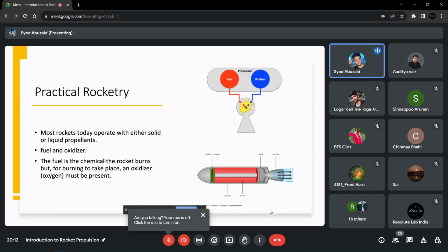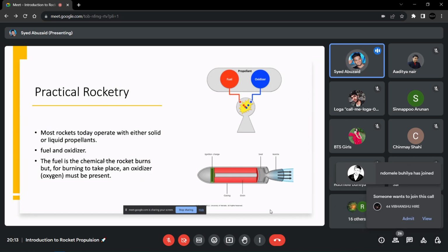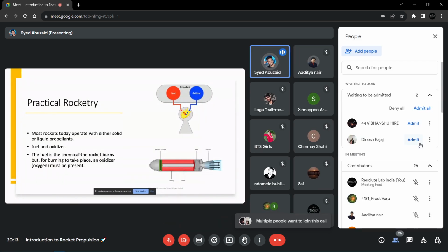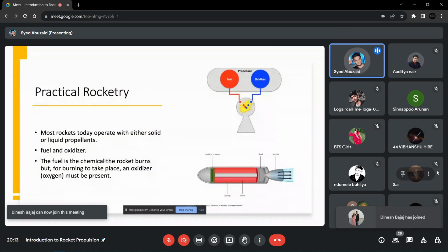So nowadays, in liquid propulsion, they are using hydrogen and oxygen. They are mixed together in the presence of an oxidizer, oxygen. Then when we ignite, it expands and comes out through the nozzle. In the combustion chamber, they make a very large pressure. If you know Bernoulli's theory, if we increase the pressure, then after the nozzle the velocity will increase. It is just the opposite reaction: pressure will increase, then the velocity will increase; if the velocity increases, then the pressure will decrease. Okay, I am telling you in a simple form.